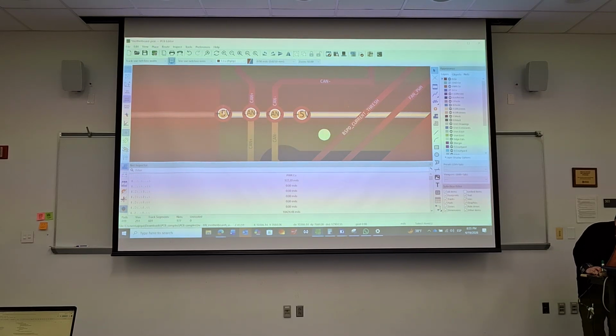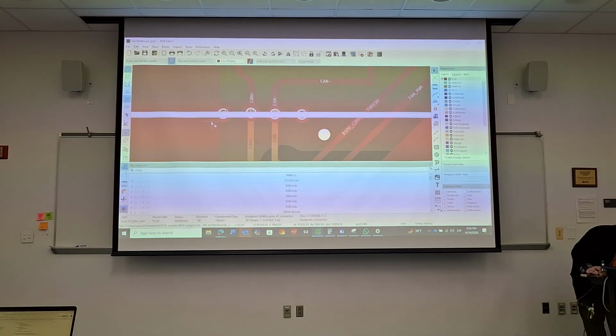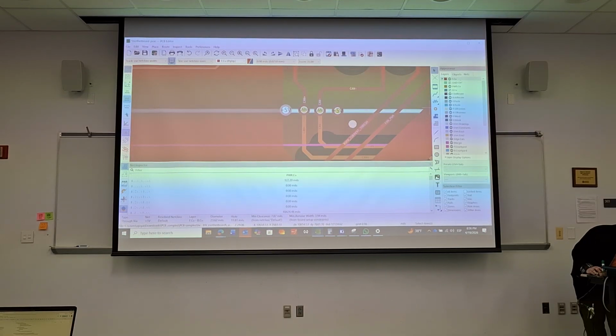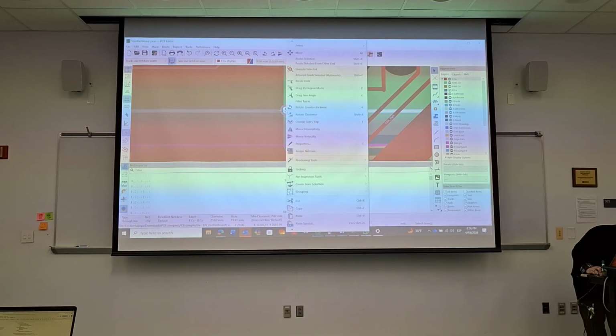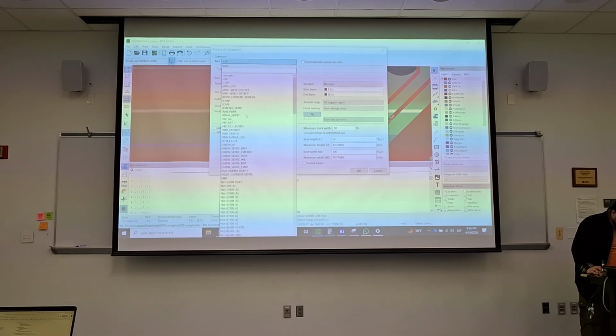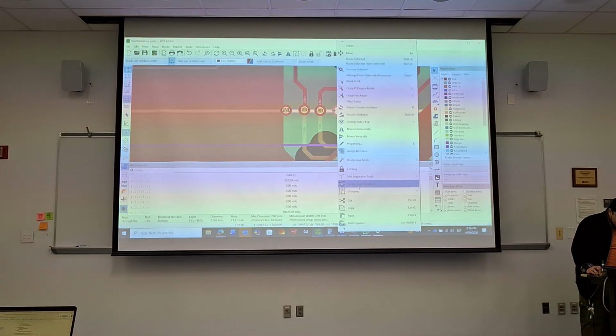You wouldn't use 5-volt vias. Let's see. I forget how to do this, but you would want it to be ground vias regardless, and you should have a ground layer. Press E? And then change the direction. Yep. I need to refresh myself with all the key bindings.